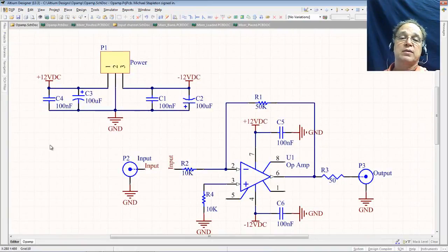So as I look back at our little op amp we're building here, our little amplifier board, I have bypass caps here to protect myself from what's coming in from the external power supply. I don't know what it is, so I want to clean it up here. This will give me a surge current that's slower. This will take care of surges that are fast. And then I have bypass caps right next to the op amp to help take care of the problems of long traces moving all over the board from the power supply.